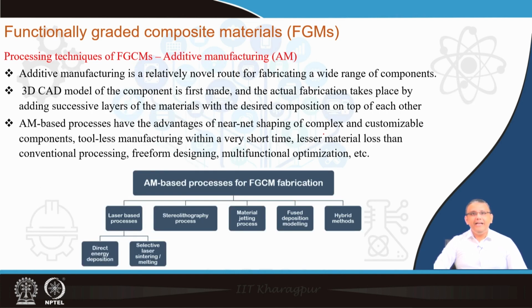Finally, the new technique of additive manufacturing has been very popular for FGM materials, and as you know, AM is a novel technique where we first prepare a 3D CAD model of the component to be designed. Once this CAD model has been designed, the material to be deposited is put in a layer-wise fashion, and once one single layer has been deposited, the table on which the component is being built moves down by a certain amount, and then the next layer is deposited. This way the whole component can be built in a systematic fashion, and this has many advantages over the conventional processes.